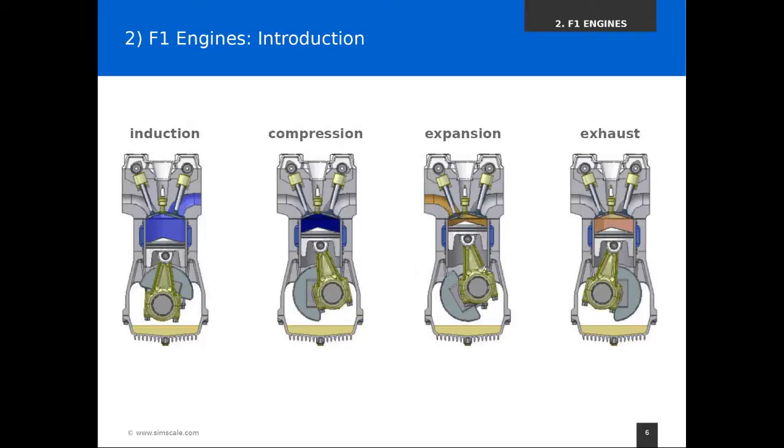And, well, I guess you can imagine what comes next. The crankshaft just turns a little further, and then it allows the piston to move down again. And when the piston can move down, it's actually being pushed downwards by this very hot gas that we have here. So the temperature and pressure are still very high. It pushes down the piston, and this is what creates the force, and in effect releases the power to the crankshaft, and then, well, this is actually how the power goes outside. And then everything repeats all over.